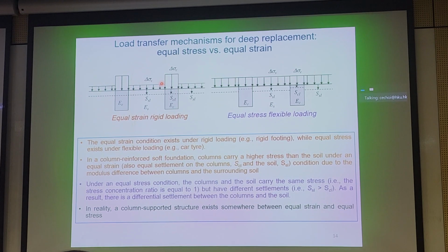And it's up to the geotechnical engineer to design whether you want to control stress or settlement. If you plan to put some sort of loading on these columns, you probably want to study very carefully what the stress induced on the columns are. Because if they fail catastrophically or brittly, you're not going to have any warning, whatever infrastructure you're putting on top.